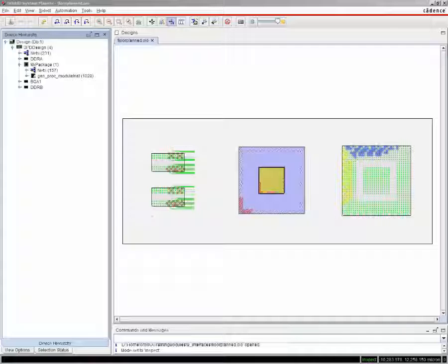The BGA on the right and the memories on the left were in the original board file in Allegro PCB and were imported into Orbit.io as a reference point to assist in the optimization of the center BGA pins and die bumps. The center BGA was created dynamically in Orbit.io, and the die was created in Cadence Encounter Digital Implementation System place and route environment and transferred to Orbit.io as a die abstract.